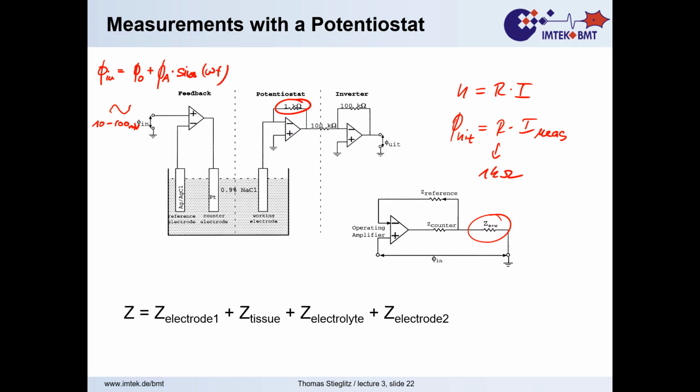I mean 10 millivolts at an electrode impedance of a mega ohm is not very pleasant with respect to the current that you expect. You are at very tiny currents there, and that's sometimes the challenge, that you need shielding, so that your laboratory lamp is not overtaking the measurement instead of your device under test.